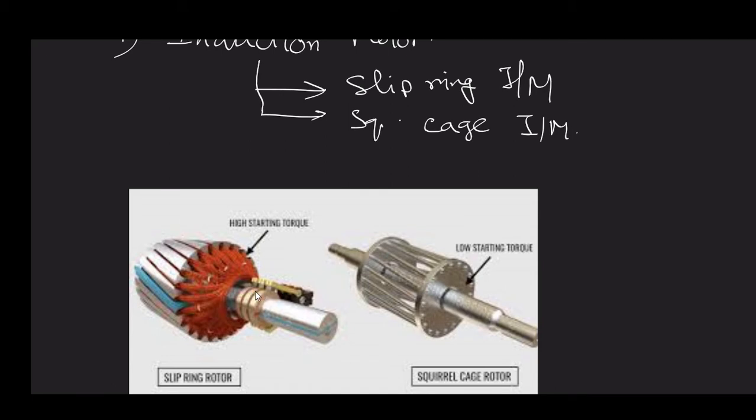These are the three slip rings you can see for these three different phases. So you will have a choice. You can short them directly, or you can insert additional resistance, reactance, or any additional electric circuits. Even you can connect some three-phase power source with these slip rings. That will be your choice.